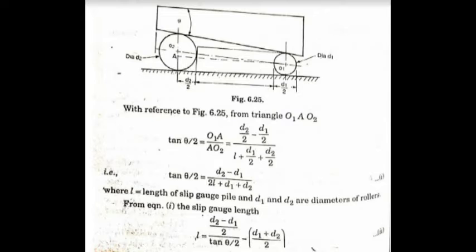If the angle of the piece is alright, then the top edge will be parallel to the surface plate and the dial indicator will show no variation when traversed along its surface.